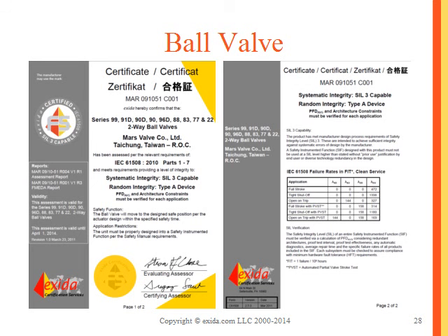And the third one here, open on trip, and then the same set of applications with partial stroke data. Again, the product name, the manufacturer, the certificate number, the systematic capability. In this case, apparently the manufacturer is also capable of achieving SIL 3 from a development process and quality system perspective. Doesn't mean that the product can be used in SIL 3 without any redundancy. Most likely you will need redundancy. And that's an example of this particular case, a ball valve certificate.